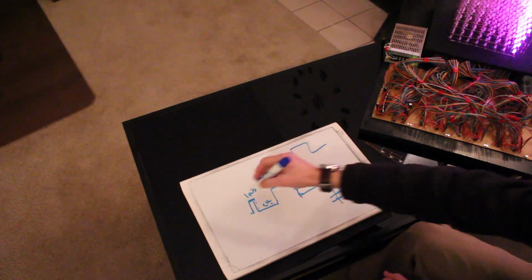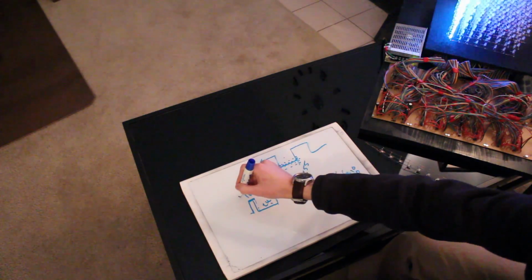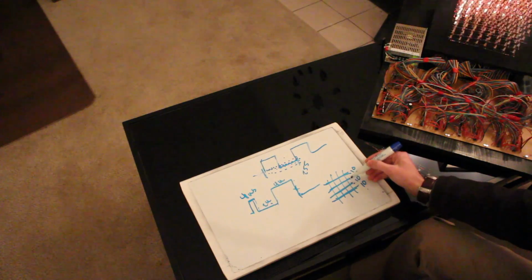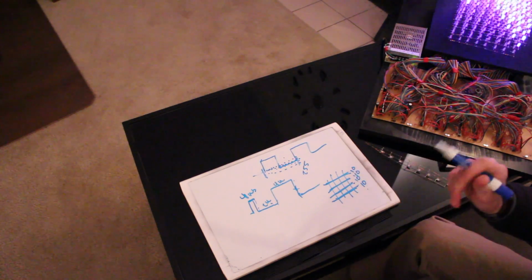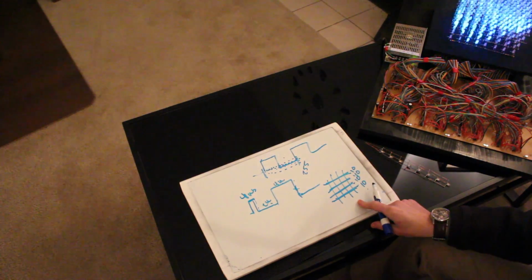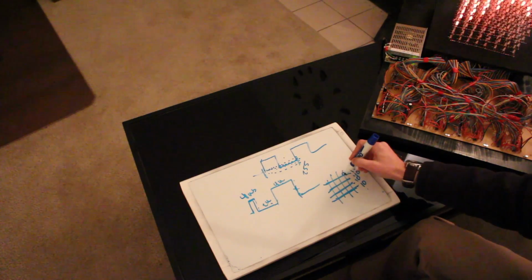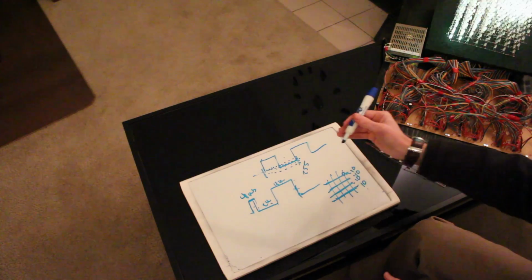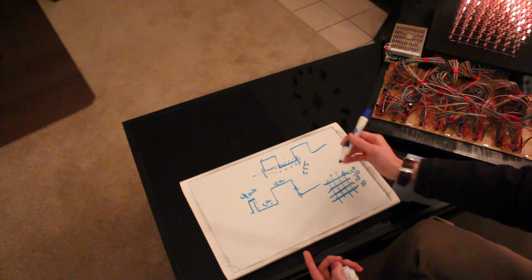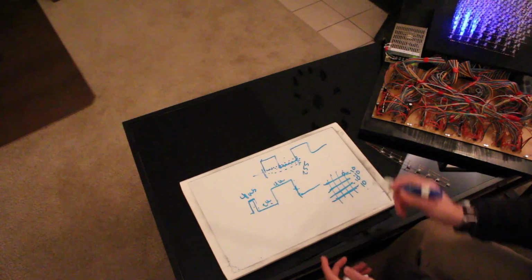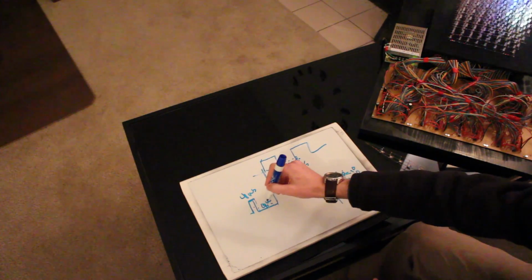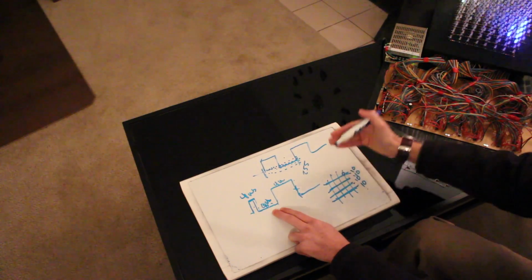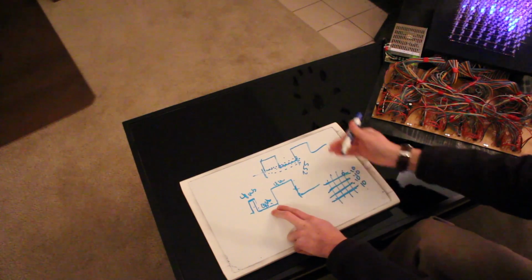So what I would do is make this 4, my minimum time of 4, so that at least each row could have a 1 in its value for the modulation. Each one would have a chance. If I wrote this one to a 1, on the first pass, it would light up. Then we go to the 2, then the 3, the 4, and eventually this would become an 8. As soon as the timer becomes an 8, then we're in the off time. So then all those would be off, or this one would be off.